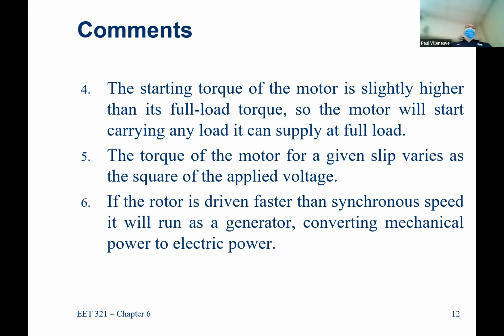And this is how you get a wind turbine generator. If you can spin it faster than synchronous speed, then it creates energy. It's a generator, not a motor. Most wind turbines, not all, are called doubly fed induction generators. We'll talk about that in a little bit. But as long as you can get that blade or the shaft to spin at a faster rate than the magnetic field that is rotating along, you can generate electricity.